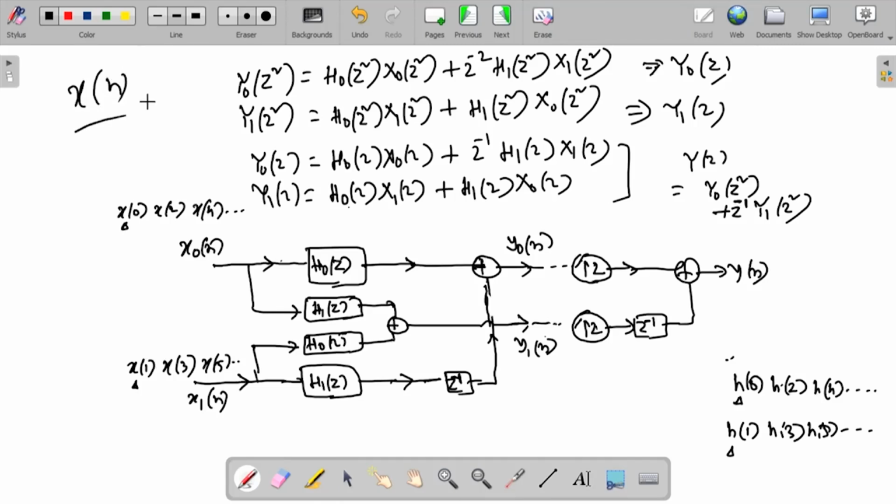One thing is in DSP you download it, decimate it by a factor 2 and all that, and similarly you can generate this, but actually you do not do that. If I have the same buffer which I used in unfolding x[n], and it is T by 2 now, T is the sampling period, clock period of the system, T by 2 shorter period, faster rate of the input. Okay. So, in the first T by 2, x of 0 comes, next T by 2 x of 0 here,